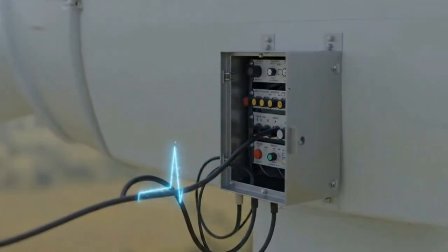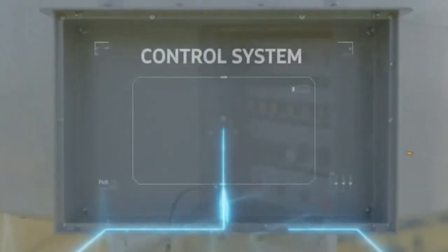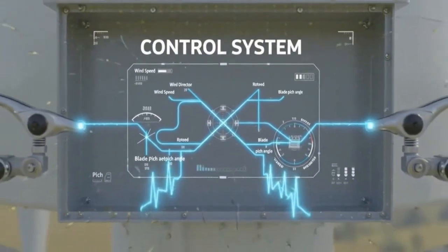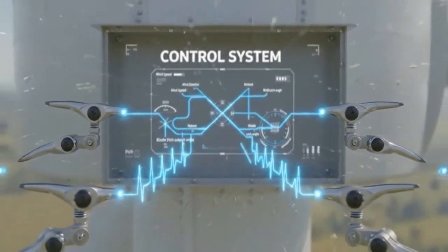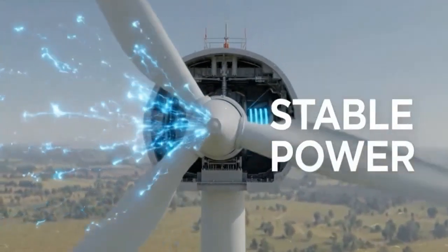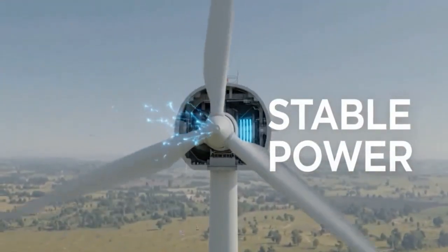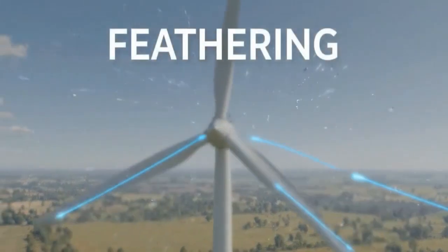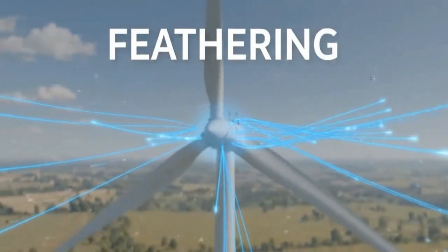After understanding the electrical path, we return to a crucial control feature, blade pitch adjustment. At the root of each blade, the pitch mechanism allows the blade to rotate around its own long axis. Changing the blade angle by only a few degrees can change how much energy the blade captures from the wind.